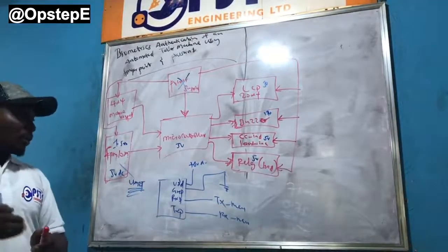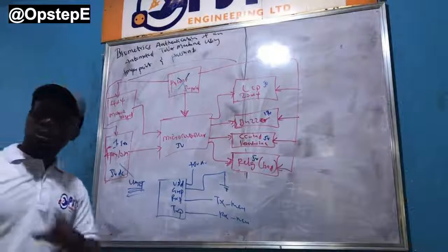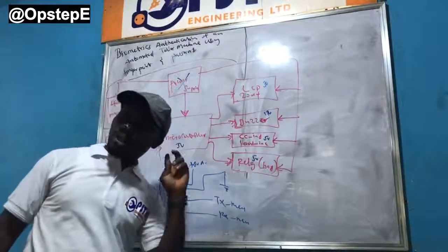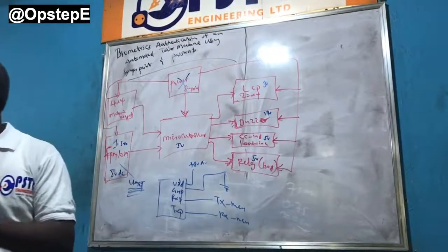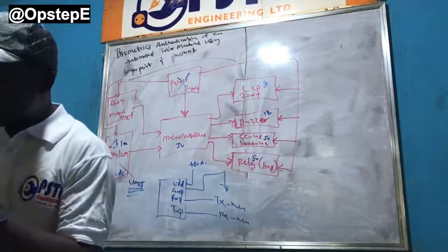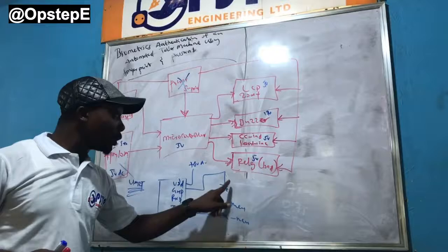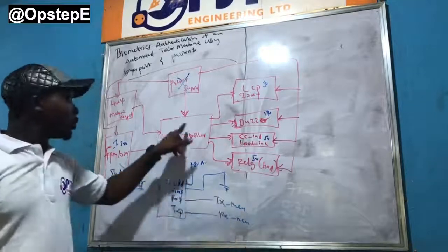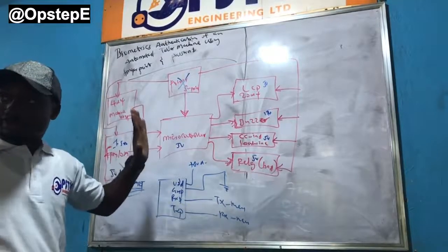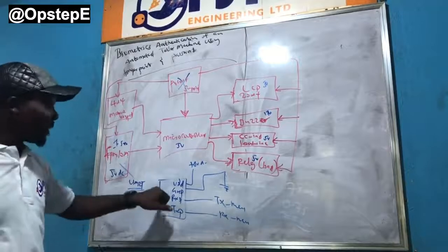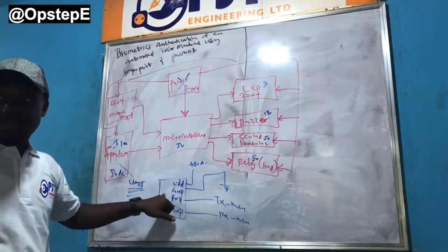But don't forget, for UART to work, your transmitting module and your microcontroller must share what? Ground. And so I want to connect this to ground. You have already connected it to the ground of this one. So clear? That's all you should know.